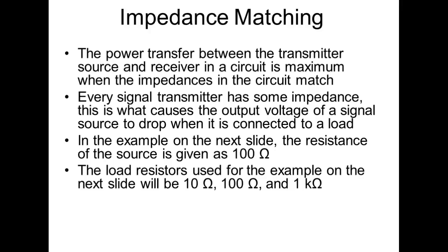And also communication cables. We don't want to put these things in knots. The bend radius is really, really critical on these cables, because if you get them too close together, you're screwing up the what? The impedance of the cable. You don't tie them in knots. When you roll them up, you don't pinch them. You roll them in nice loose loops, because, what's that?